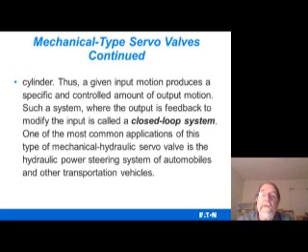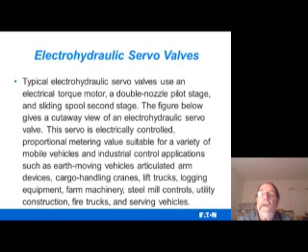One of the most important applications of this type of mechanical hydraulic servo valve is hydraulic power steering systems of automobiles and other transportation vehicles. Electrohydraulic servo valves. These typically use an electrical torque motor, a double nozzle pilot stage, and a sliding spool second stage. The figure below gives a cutaway view of an electrohydraulic servo valve.